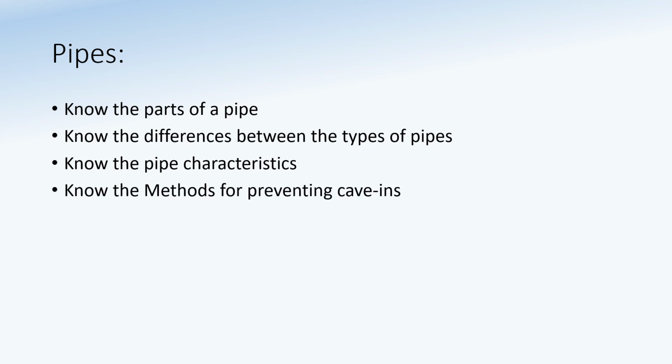And then know the methods for preventing cave-ins. We talked about shoring, sloping, shielding. Scaffolding is not one of them.